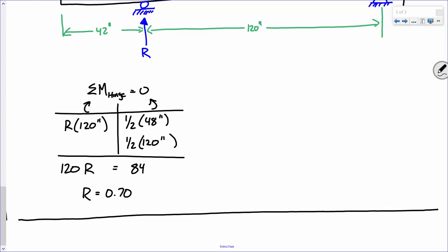Okay. So my lever rule analysis generated a reaction, a distribution factor of 0.7. Or actually, no, I'm saying that incorrectly. My lever rule analysis generated a reaction of 0.70. That's not the distribution factor because we haven't applied multipresence yet. Talk about that here in a second. So far, so good?